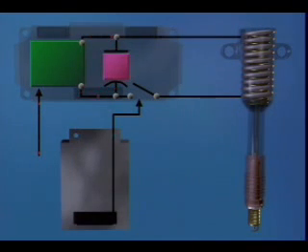As discussed earlier, when the piston reaches the correct spark advance position in the compression stroke, the ICM closes the switch to the ignition coil. The ignition coil then delivers this high voltage to the spark plug.